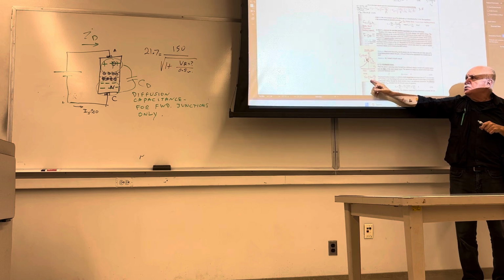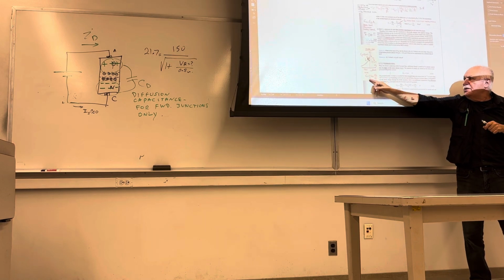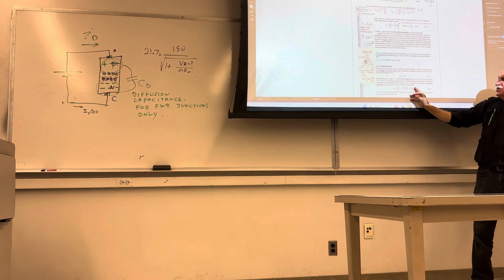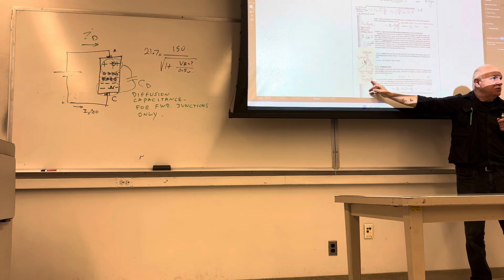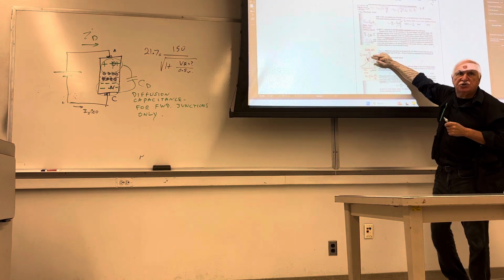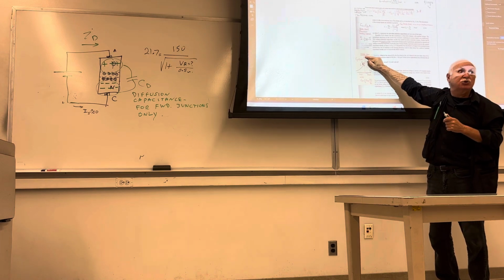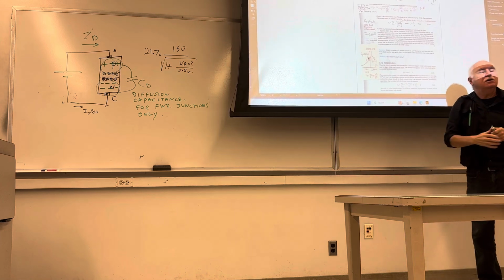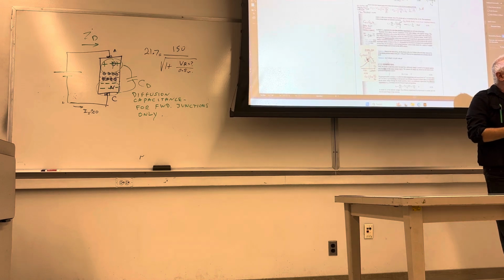So, if you want to express this capacitance in terms of the VD, substitute, and then you will see CD becomes exponential function of the forward voltage. That's why this curve that you see over here, increasing, is actually exponential, very rapid, meaning it will give you very large forward capacitance.